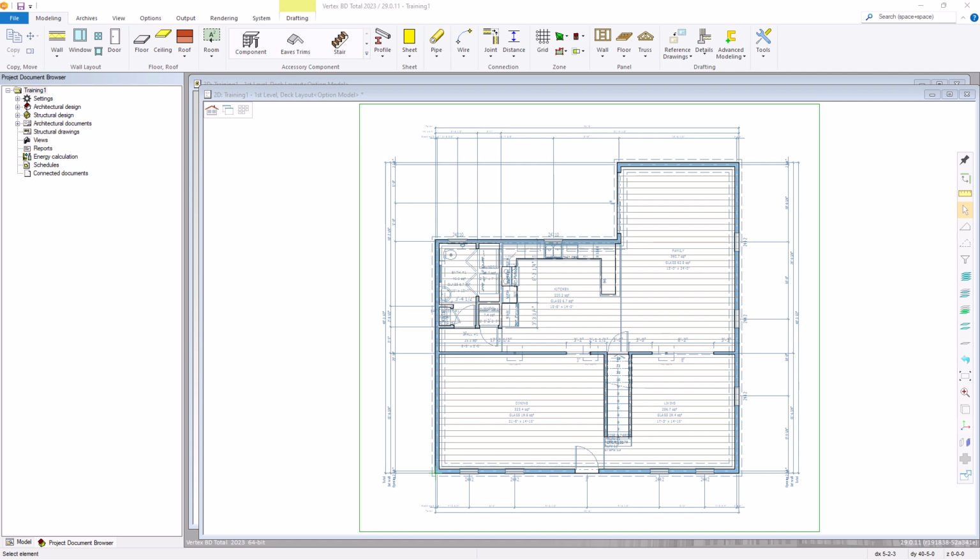Before we generate our floor framing, we need to determine the direction of the floor joists and how they will be supported. We'll have the joists run front to back. Over in this area, we'll have them run left to right. For support beams, we'll add a drop beam over the family room. We'll add a flush beam to support the floor joist along this wall. We have 3 columns in the basement that will support that member.